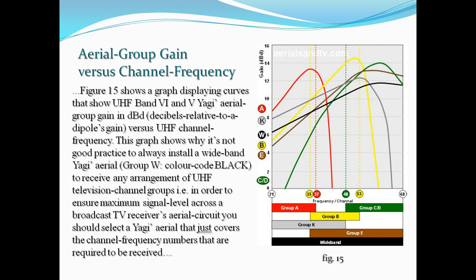In some areas of the country, channel spacing has to be wider and group A, B or CD aerials can't be used because of interference problems from transmitters in adjacent television regions or within your own television region in some cases, and the frequency planners who are providing the transmission facilities for the ITV companies and for the BBC have to space the channel numbers out further than what would be desirable for using group A, B or CD aerials,